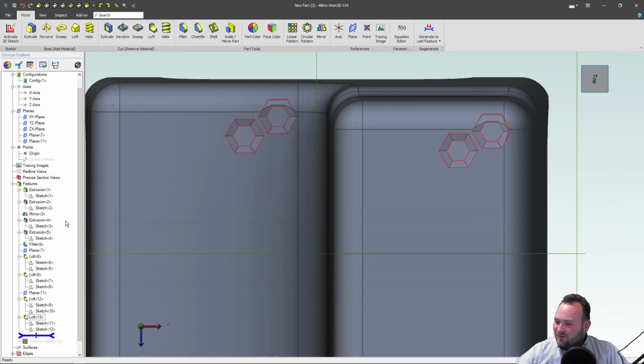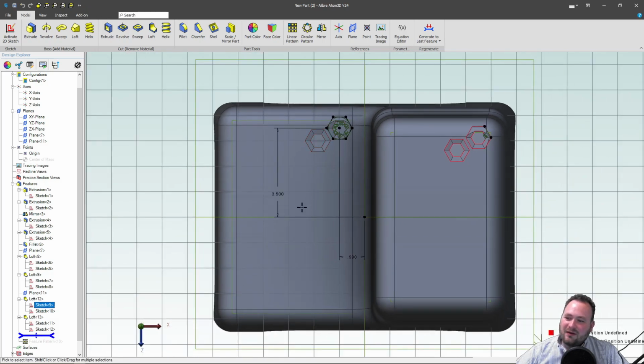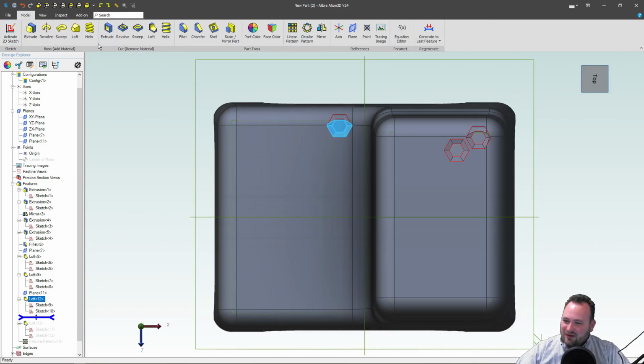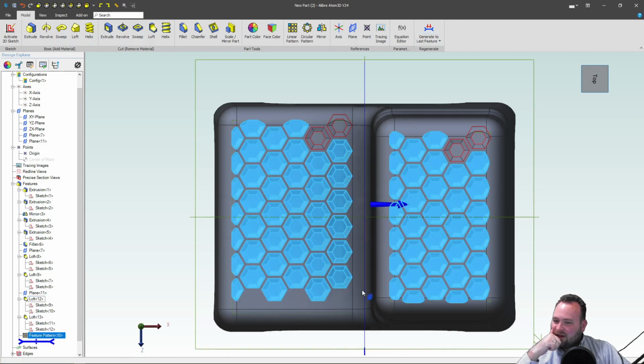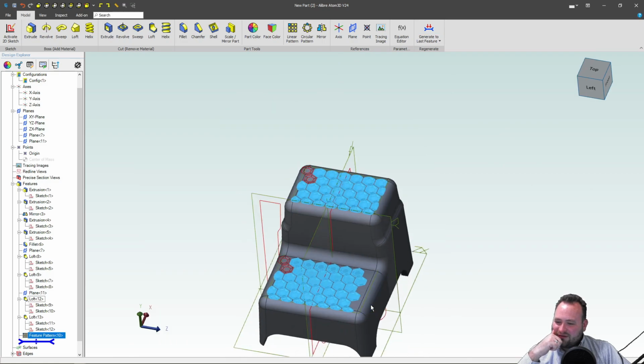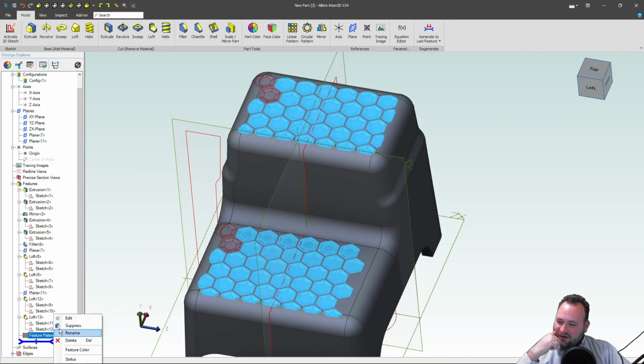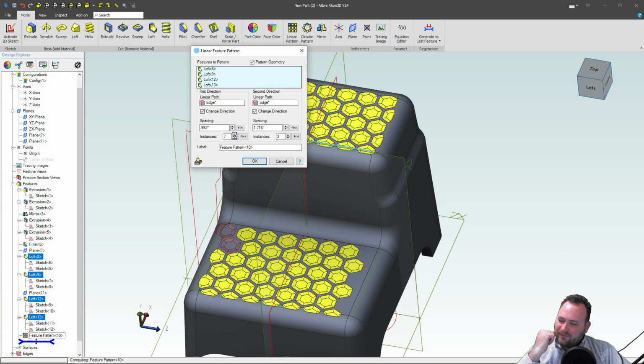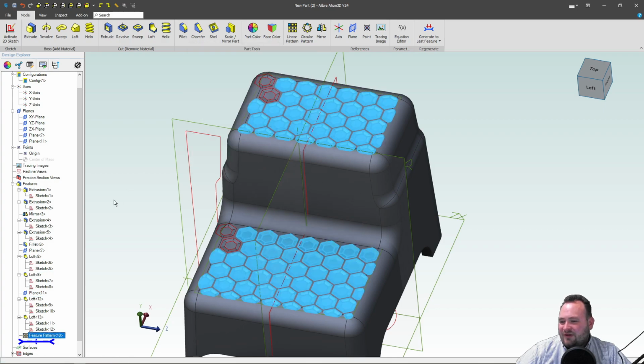We can go even a little bit further on sketch 9. 3.6, right? And that way our pattern seems to be pretty fully in there. We'll generate the last feature now. Good, and since we have a wider base, you can see we're missing a few hexagons on that side, and that of course is an easy fix. We're just going to go from 7 or 8 to 1 more. And there it is, right? So now we're looking complete on that.